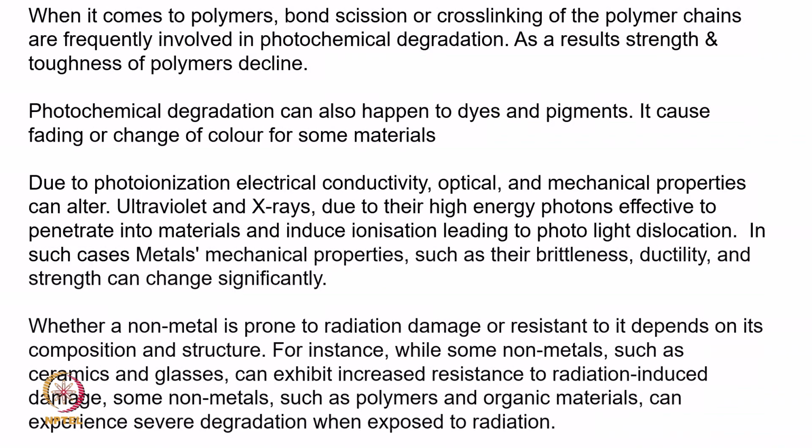We will cover in this lecture a few examples of how the brittleness will increase because of exposure to radiation. As the brittleness increases, naturally ductility will come down, and it will also cause some loss of strength. Now, if you think about non-metals, like glass or ceramic, because they have a high melting temperature, they may not get affected that much by the radiation, or maybe only a low temperature rise.